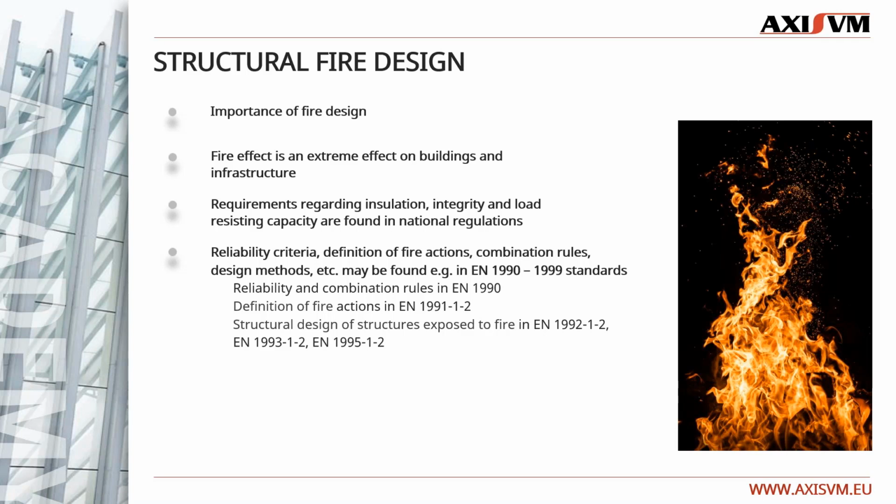According to structural fire design and structural reliability, we can find reliability criteria, definition of fire actions, combination rules, design methods, and others in, for example, the Eurocode standards, and in more detailed form: reliability and combination rules in Eurocode 0, definition of fire actions and fire rules in Eurocode 1, and material-specific rules may be found in Eurocode 2, Eurocode 3, and Eurocode 5.